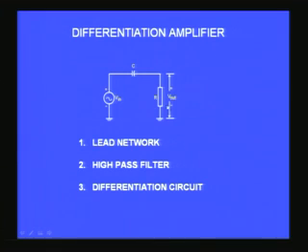When you do that, it can also be considered, as you might perhaps know, a high pass filter, because when the frequencies are very large, the reactance offered by the capacitor, which is inversely proportional to the frequency, will be very, very small, and therefore almost all the voltage will go through the capacitor. It will become almost like a short, and therefore what you get will be a full output.